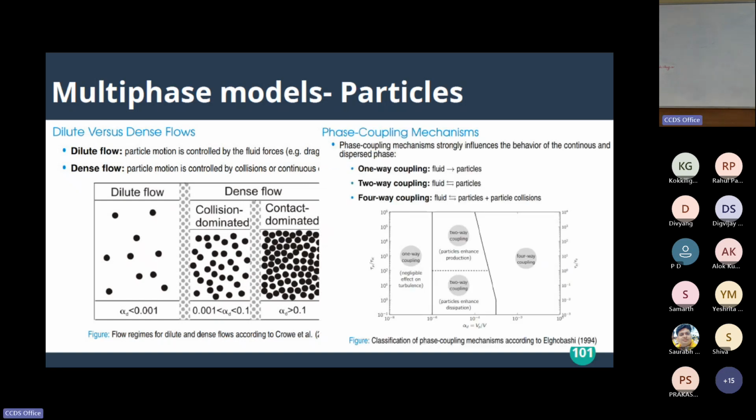So based on that, people try to plot the size of the particles, the volume fractions they are using, and what kind of characteristic flow scales are involved in that problem. Based on that, people realize: do I need to fully resolve? Do I need to one-way couple, which means particles will be advected by the flow, or can particles rotate and affect the flow? This kind of thing people usually go through. Though the numbers are not important, that kind of plots are available. Based on that, one will be in a position to sense which regime they are in and what is the correct method one should use.